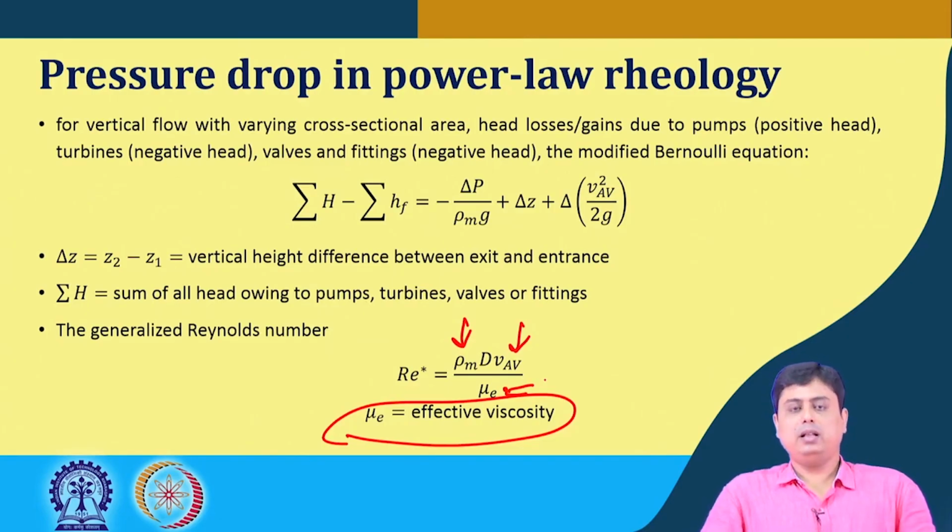So one part is to calculate the Reynolds number of the existing slurry that exhibits power law behavior. The other part is what the transition Reynolds number is in such a slurry, because for the Newtonian case we know that the margin is 2000 or 2100.